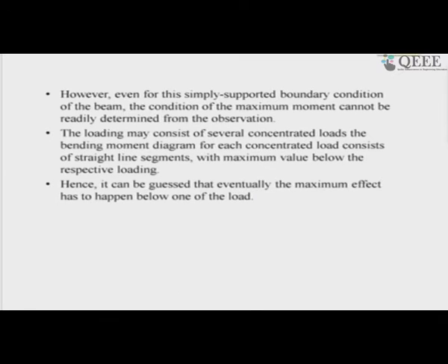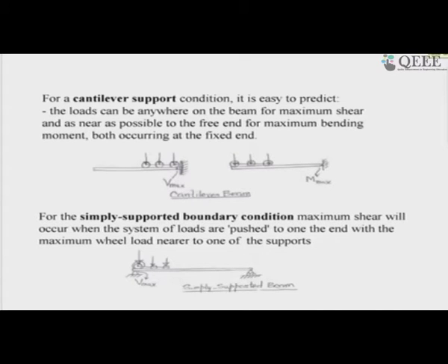And then the absolute maximum bending moment and shear force: it is easy for the cantilever, for both shear and bending moment. Do not forget that depending upon the relative positions of load, if you are allowed to change, suppose the vehicle can come from this side or this side, then the condition will be different. I will always place the maximum load at the extreme end. It is not shown in the book, so you have to just understand engineering intuitively.